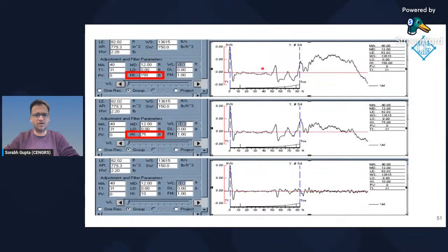Let's move forward. So this was when I used a high pass of 150. If I further reduce the high pass, I use a high pass of 75. This is what the data looks like. And that's good. Now here, this is very good data. I have almost completely eliminated the effect of soil resistance. Now this signature is purely carrying information of changes in impedance in the pile shaft itself, in the structural aspect of the pile itself.